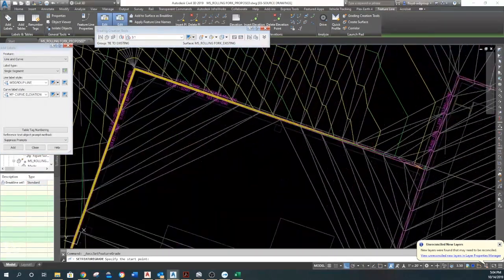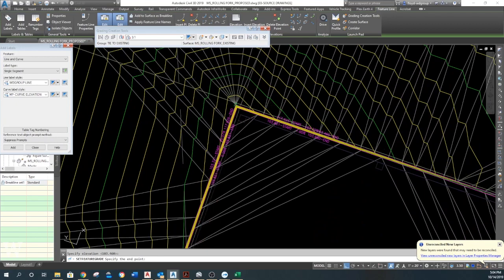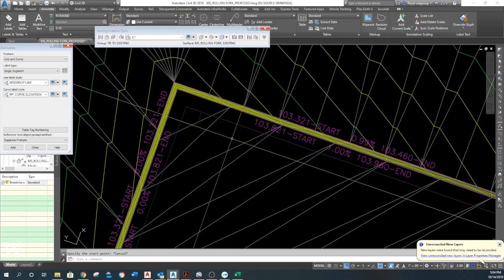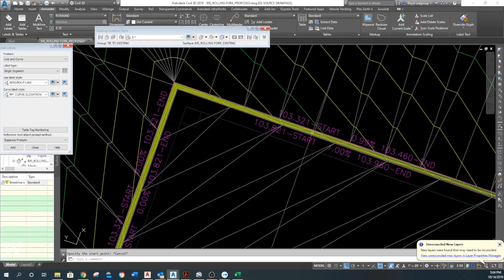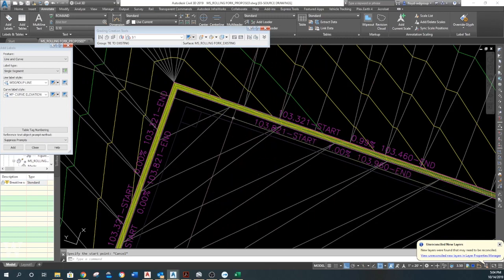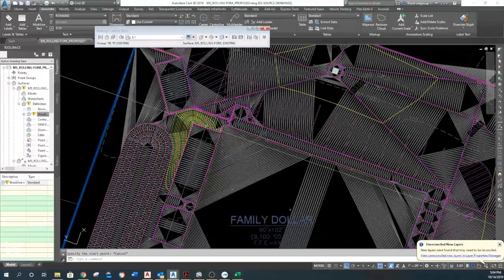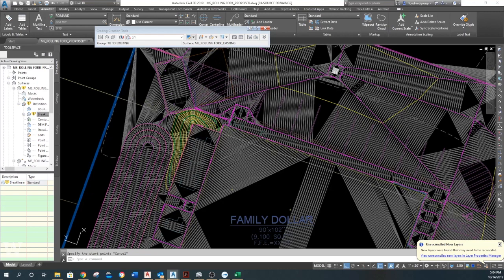We could do elevations. We can click it right there, and it should be 6 inches lower than that. 3, 2, 1. Probably what happened was I was supposed to pick elevation, and I put a grade slope in there or something. That's the reason it was weird. Okay, but that's what I said. You'll know when you mess up, because that's why you keep all your lines at 0, because you'll know when you mess up. It'll show up somewhere.